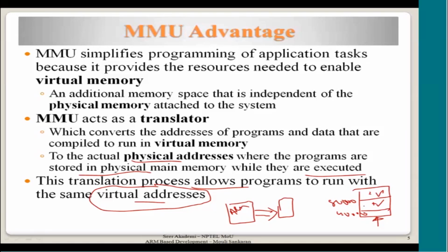Similarly, if the programmer thought that the code is residing in a particular location, R15 will be accordingly modified to access the original virtual address only. For example, suppose within the code there is a branch; the relative addresses it computes will be based on where it assumes the code to be. If it is an absolute long jump or something, it will generate the same address. It will replace the value in R15 with the original virtual address where the program was supposed to be residing. But because we are in between, moving it to some location which is different from this, we have to take care of it.